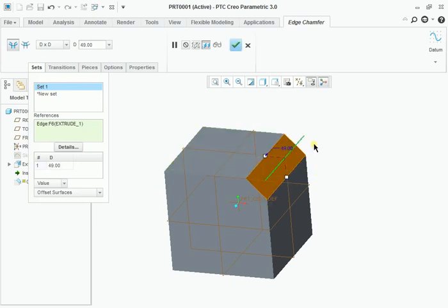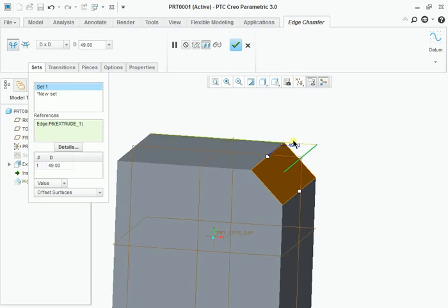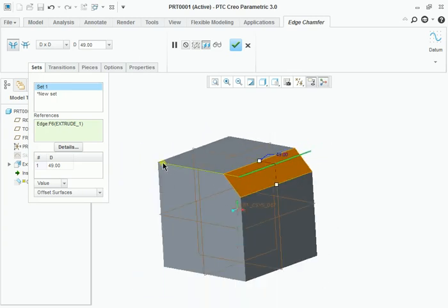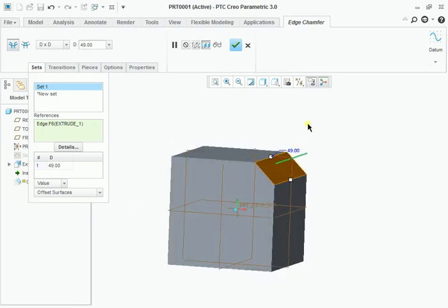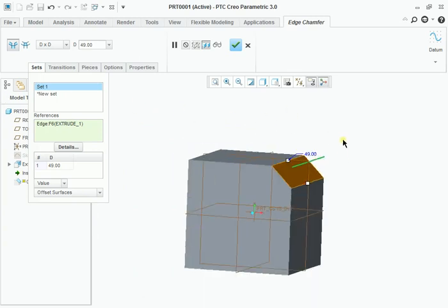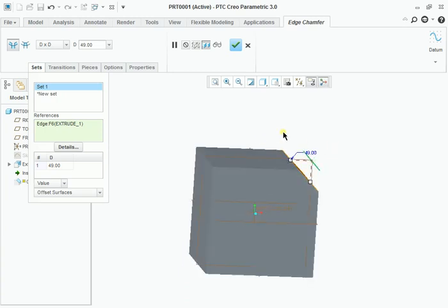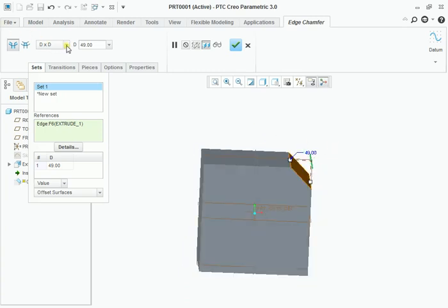So it is a basic shape. You can see that the sharp corners and sharp edges are eliminated by the bevel edges. In chamfer we have further types. Drop down here, and you can see a number of types. The first one is D x D. The distance from the selected edge to the sides is equal. And the next one is 45 x D.